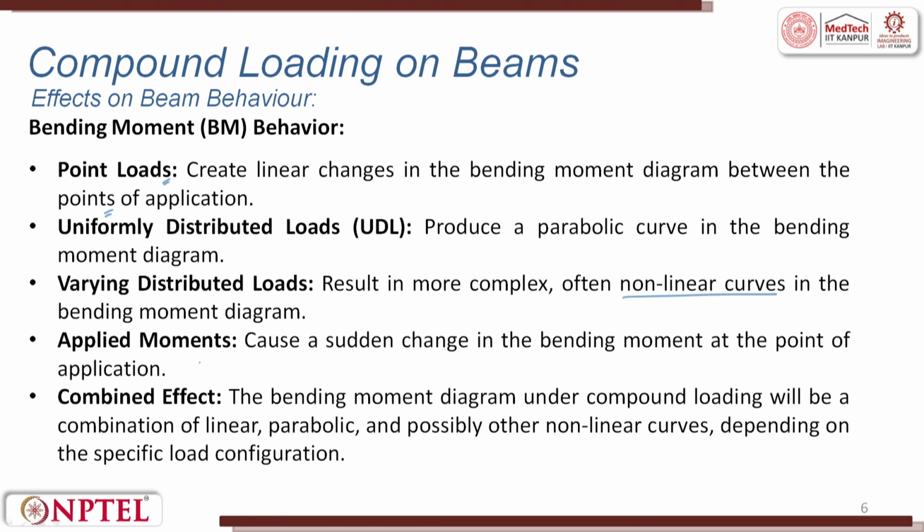Applied moments cause a sudden change in the bending moment at the point of application. And finally, the combined effect: the bending moment diagram under compound loading will be a combination of linear, parabolic and possibly other non-linear curves, depending on the specific load configuration.